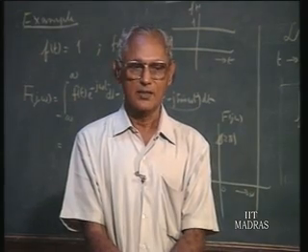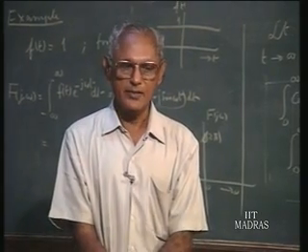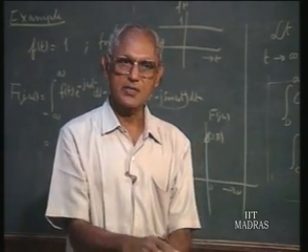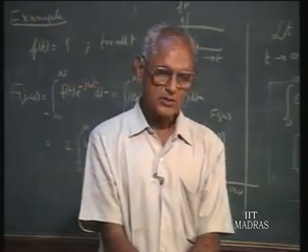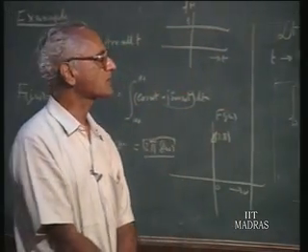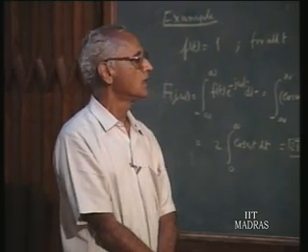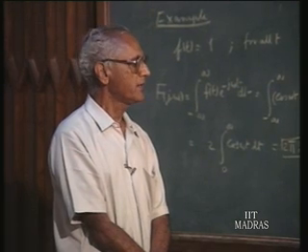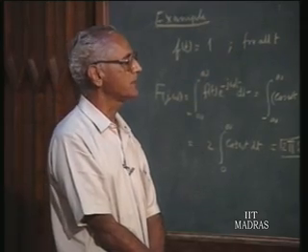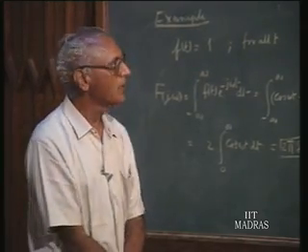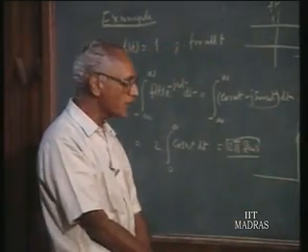Therefore, we saw that if we integrate from minus infinity to plus infinity the energy density, which is given by magnitude of F of j omega squared, with reference to omega and divide by 2 pi, because this energy density is in terms of frequency in hertz, cycles per second, that will give you the total energy. And this we said is also referred to as Parseval's theorem. Then we discussed the possibilities of extending the Fourier analysis to signals whose energy content is not finite. In that context we started with some interesting relations involving sin theta by theta functions, and we familiarized ourselves with the sine integral. Then we put down some results which are sanctified by the distribution theory in mathematics, which we cannot prove by classical methods.